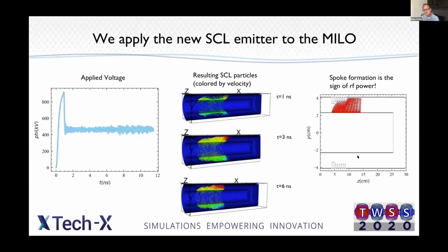You can see, though it's a little hard, that the electrons are actually running up inside those veins. That's great. That means we're getting good interaction between our input voltage and our beam. You can see structure to the beam out here. Again, that is great. That means we're getting good interaction and we can expect some RF power. So this all looked really good.